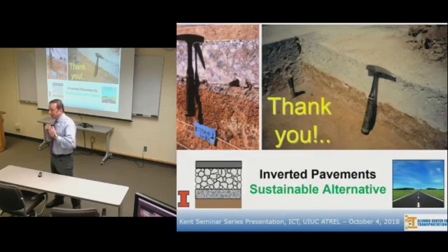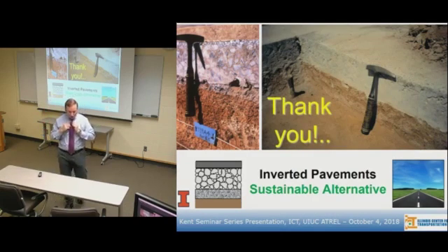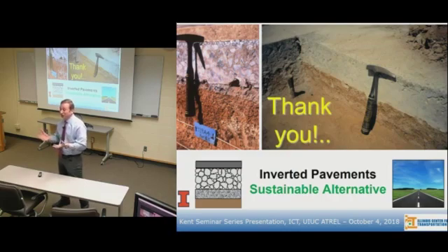That's right. The question was, again, in the South African practice, 12 to 50 millimeter surfacing on top of the aggregate base, which is supposed to be an asphalt surface, right? The 12 millimeter is our surface treatment, basically, whether two chip layers or one, but it's just 0.5 inches. That's not a structural layer. Even if the 2-inch or 50 millimeter one is a structural layer, it would be a thinly surfaced pavement consideration, where bottom-up fatigue cracking is not a problem because it conforms to the shape of the underlying support. But the 12 millimeter is surface treatment.